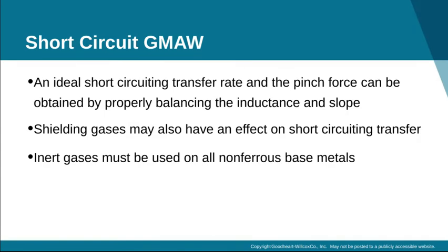Shielding gases may also have an effect on short circuiting transfer, so that's true. Carbon dioxide, or CO2, definitely gets a lot better penetration. It's a lot hotter. It's just a lot rougher of a weld than a 75-25 argon CO2 mix.